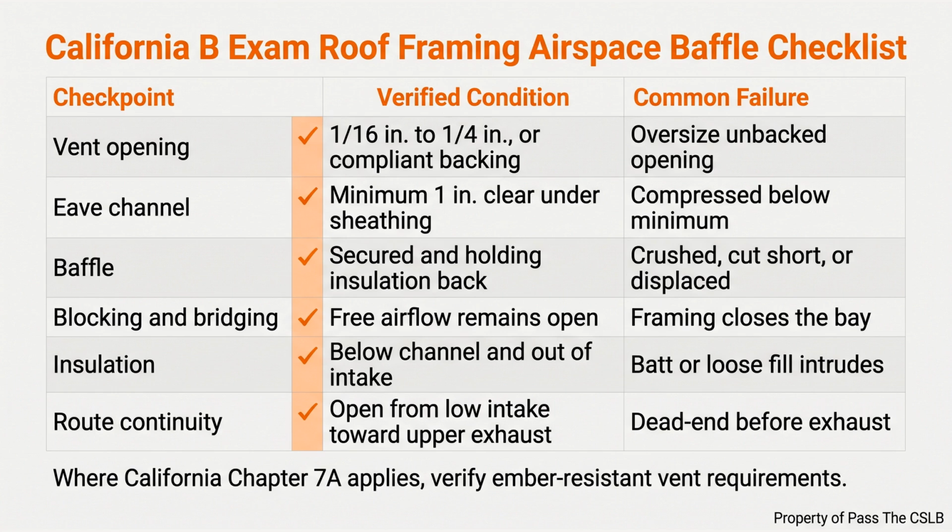The cause and effect chain is worth remembering. A ceiling leak path delivers warm, moist air. A cold roof deck brings that air to its dew point. Liquid water forms. A blocked eave channel slows drying and removal. Repeated exposure can damage sheathing, framing, insulation, and finishes. That is a realistic sequence, not a guarantee that every blocked vent produces rot.